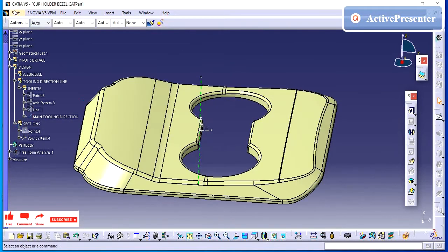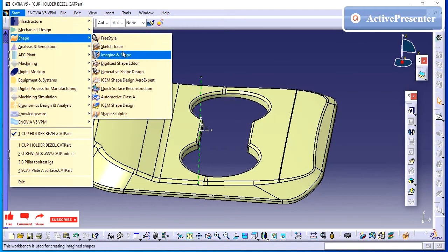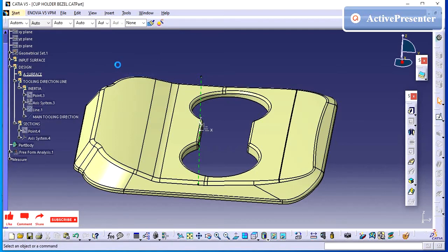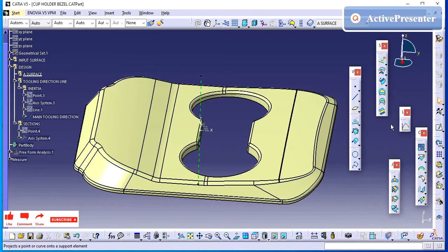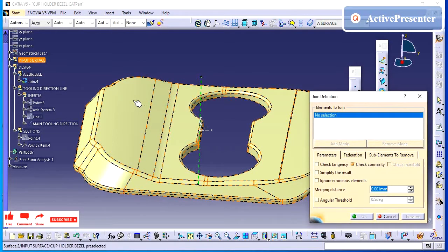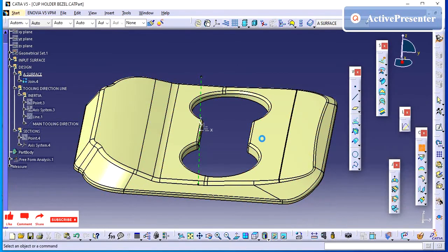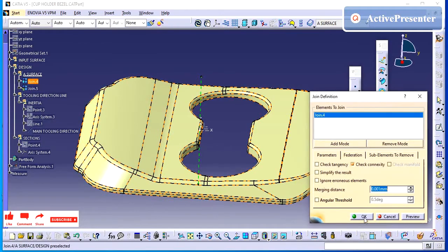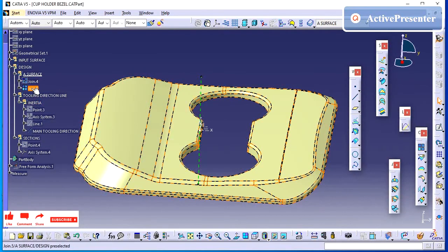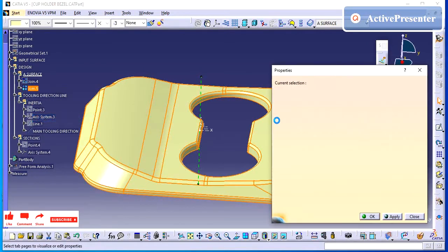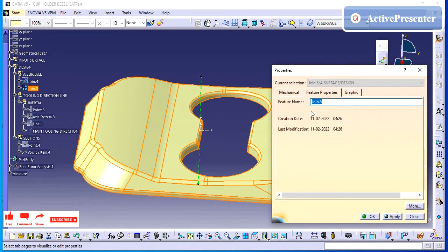This axis system is created in the Y0 plane. The part thickness for this is 2.5 mm, and the environmental parts are the cup holder and the bottom bezel.